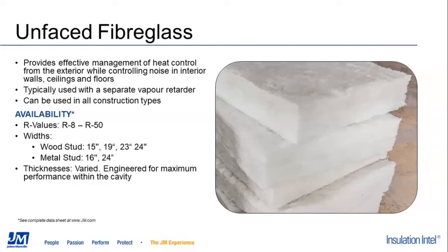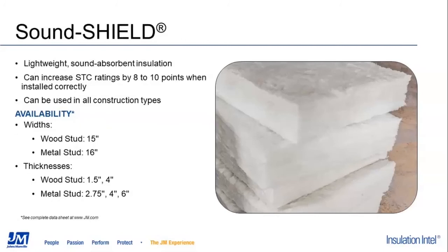So our next fiberglass batt is Sound Shield. Sound Shield is marketed specifically for sound control applications. And we do not label this product with an R value. But as mentioned in previous slides, fiberglass insulation does provide thermal and sound control, regardless of how it's marketed. This product is just specifically marketed for spaces in a building that are looking for sound control properties only, and that's really typically driven by a specification.